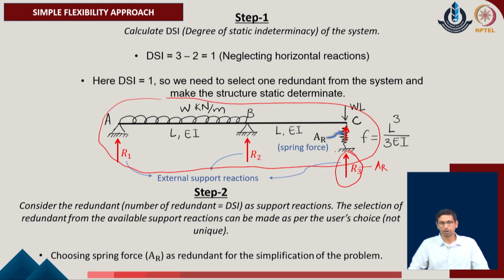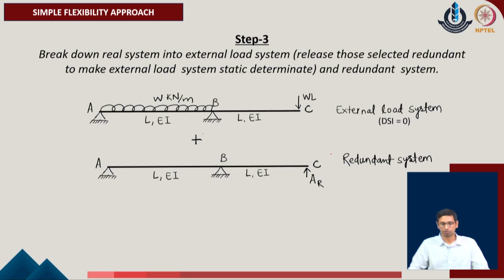So, once I remove this reaction, the remaining system becomes my statically determinate system. On the same system, removing the load, I bring in the calculation of Ar, the redundant value, and that becomes my redundant system of the given problem.